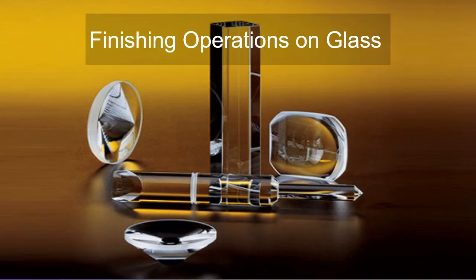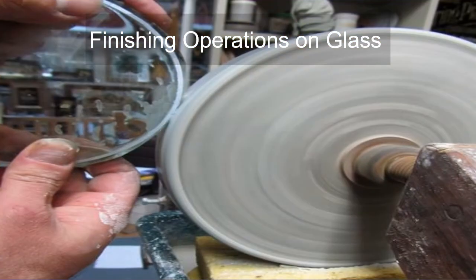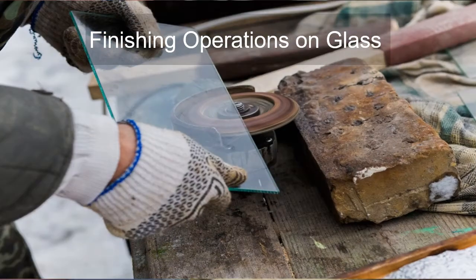Finishing operations on glass include grinding, polishing, and cutting. The glass sheets often must be ground and polished to remove the surface defects and scratch marks and to make the opposite sides parallel.